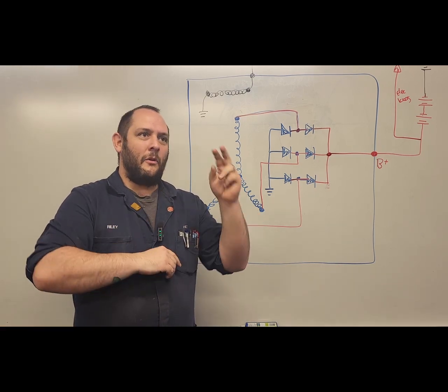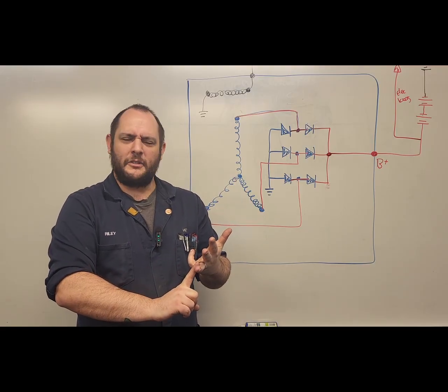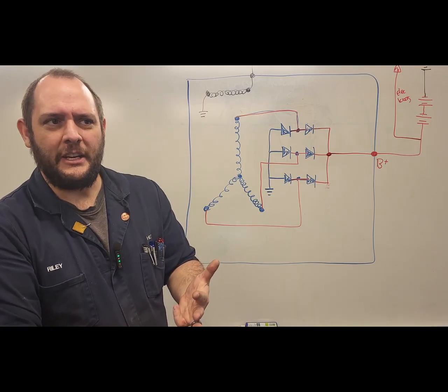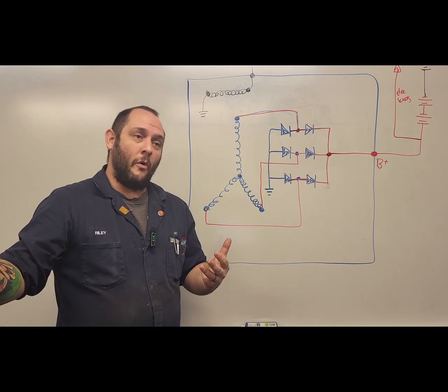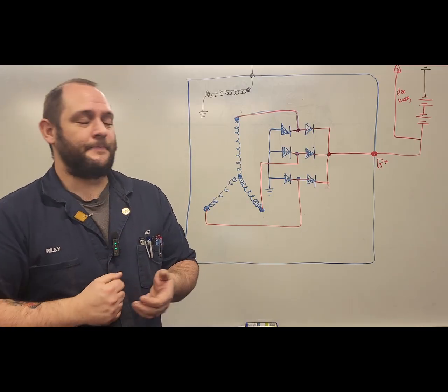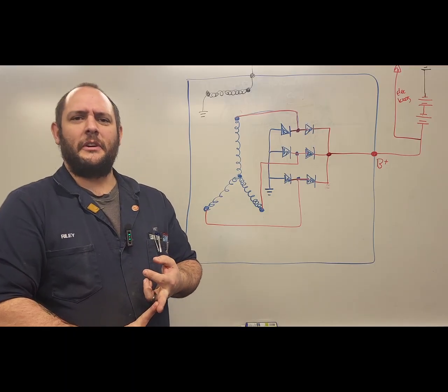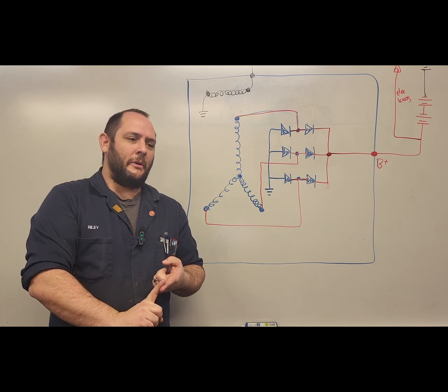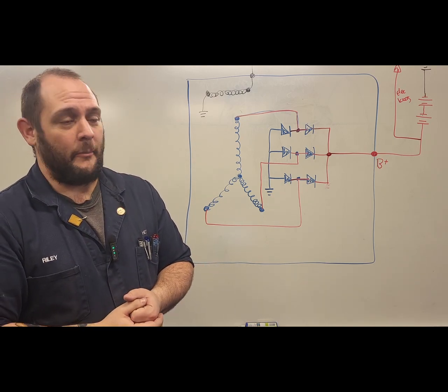I'm looking for any one of the three diode conditions that we may see. First of all, what is a diode? An electrical one-way check valve. So a good, normal operation will be flow through a diode in one direction and no flow in what we call reverse bias, or the opposite direction. Then there are the two bad diode effects: a shorted diode, allowing electrical current to flow in both directions, or an open diode, allowing current to flow in no direction, essentially opening up that circuit.